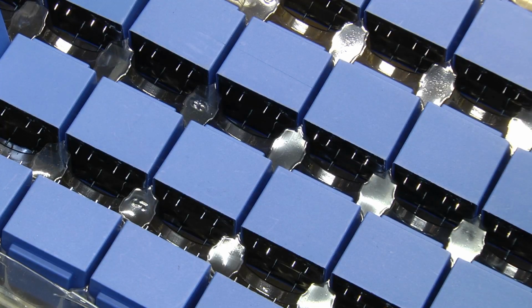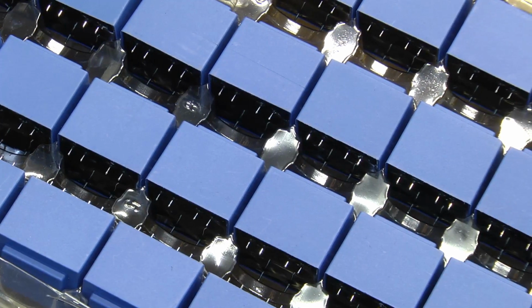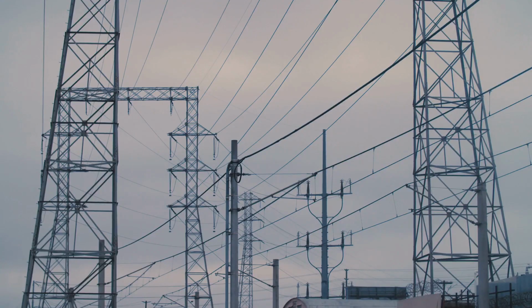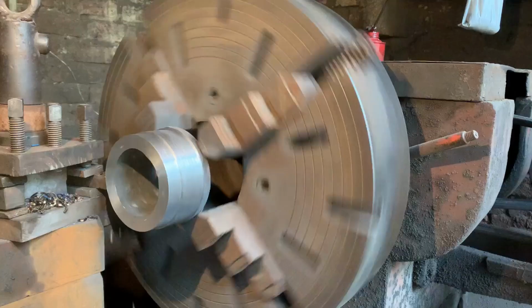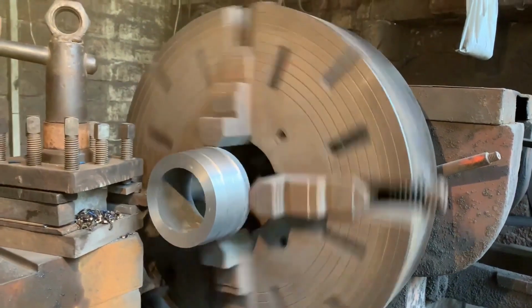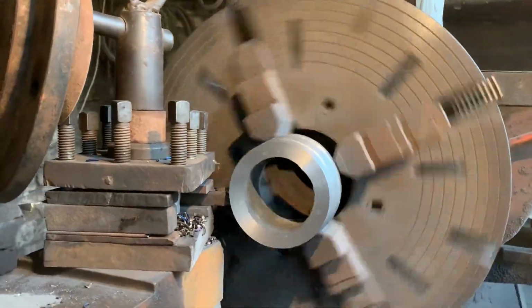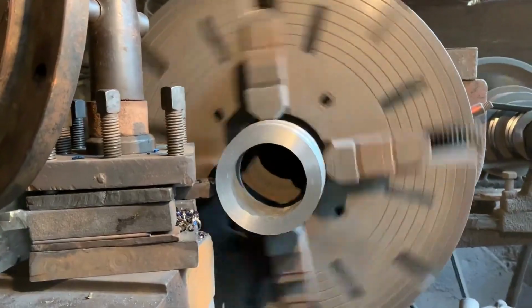In many commercial and industrial settings, you'll find capacitors installed across large motor loads or switchgear. These capacitors store and release energy to support magnetic fields, reducing the burden on the utility supply. For larger facilities, synchronous condensers, essentially large rotating machines, can also improve power factor by generating controllable reactive power.